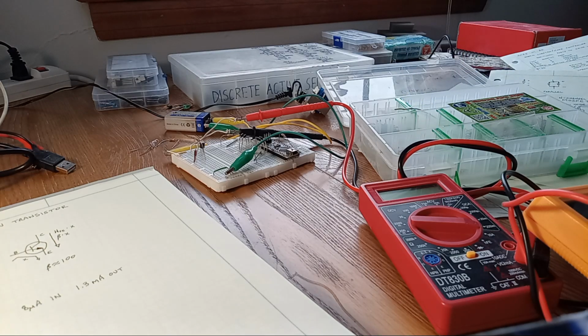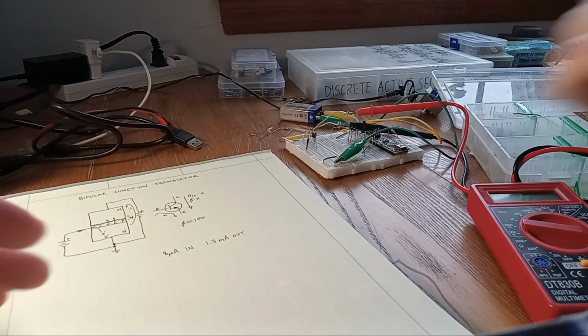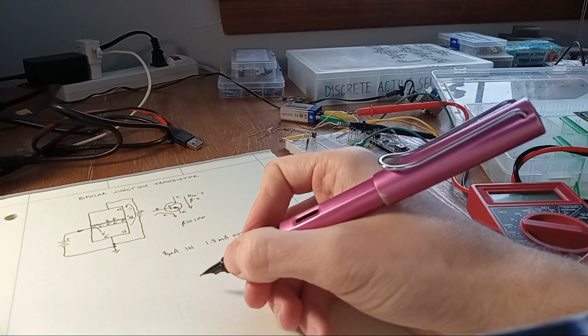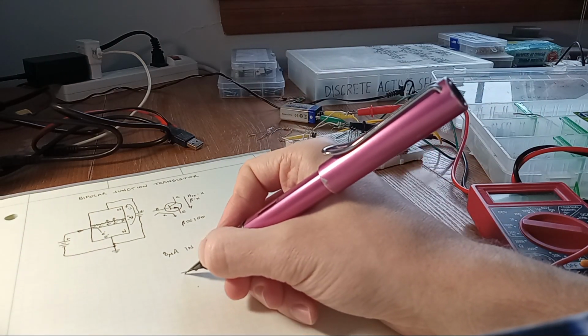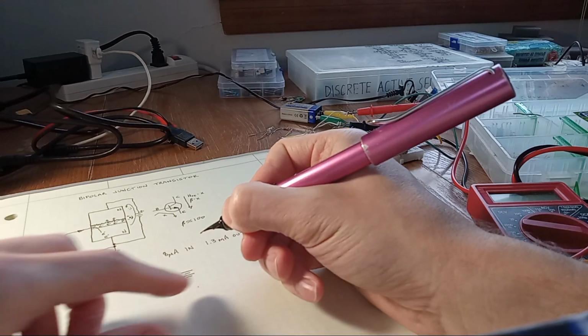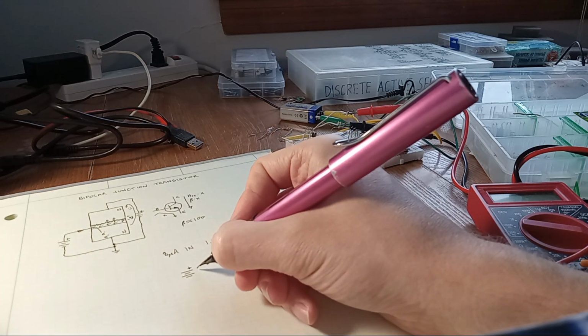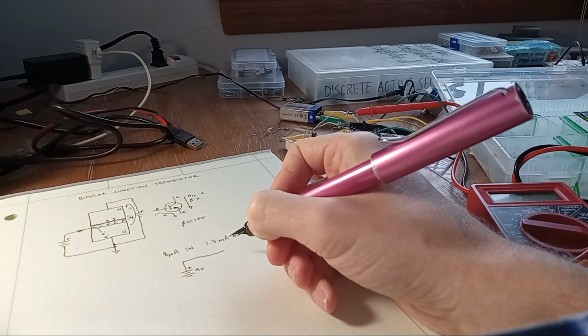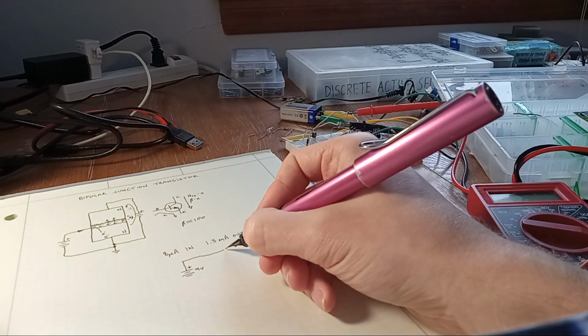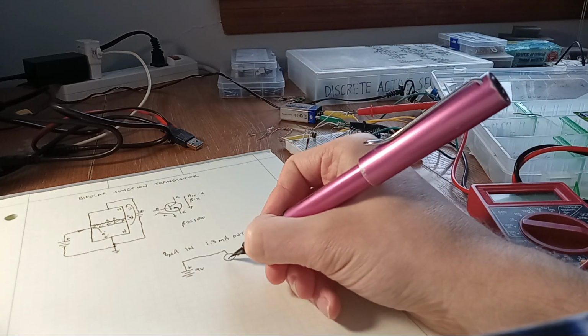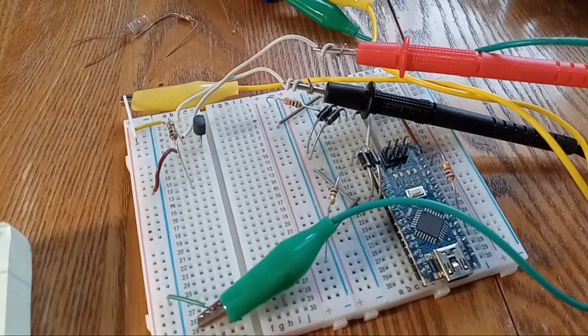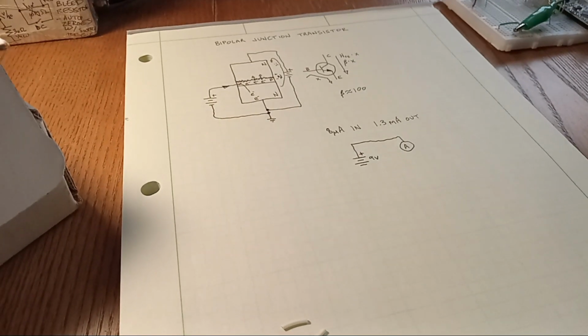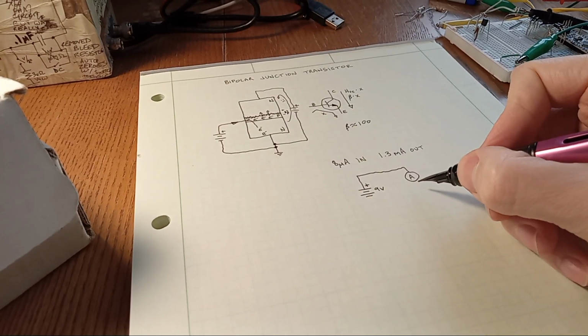So, now we can draw the schematic of what we were doing, which is always a good idea. Like all of our work so far, it starts with this lovely 9-volt battery. Then we ran it through a meter, which is a circle with either an A or a V in it. A is for an ammeter, which we were using, and then V is for measuring voltage. So we ran it through a milliammeter.